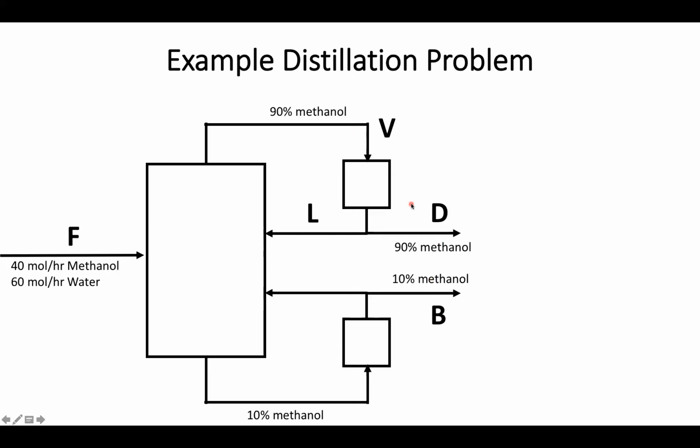This is going to help make the problem a little bit easier. If I want to figure out a lot of my mass balances, a lot of the information I have right now is focused on the overall balance. So let's start by looking at an overall balance. I know that the rate of my feed coming in has to be equal to the rate of distillate and bottoms leaving. This means that my bottoms is going to have as many moles per hour leaving as my feed minus my distillate. This is fairly useful, but you'll notice I still have 2 variables, which means I need to hunt down another equation.